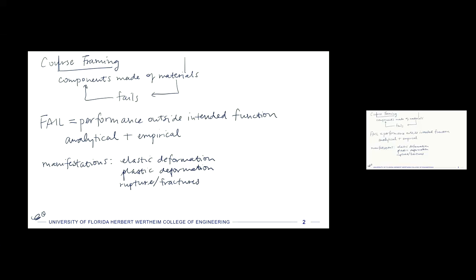You can also have a rupture, could be like a plastic collapse, where you have a big truss structure and it starts to yield, and then it yields further and further such that the whole structure collapses. And then we can also have failure due to material change.